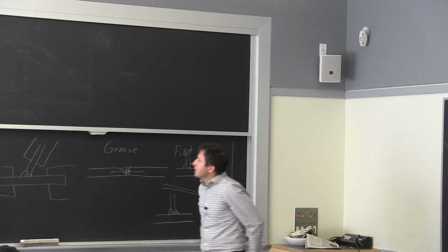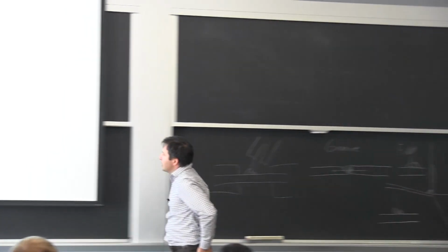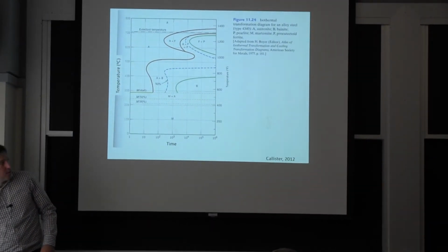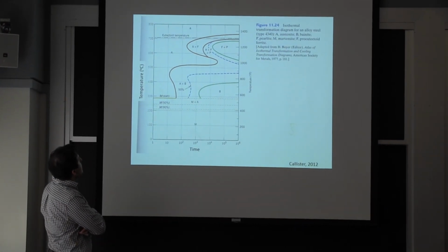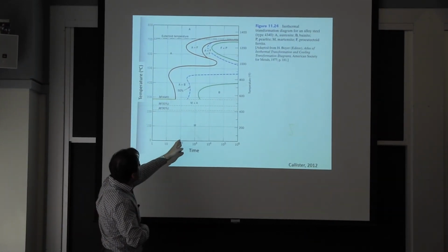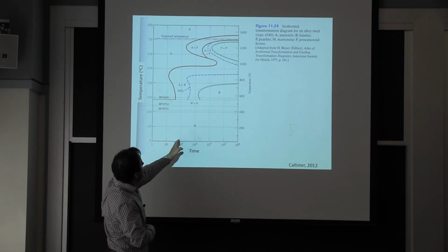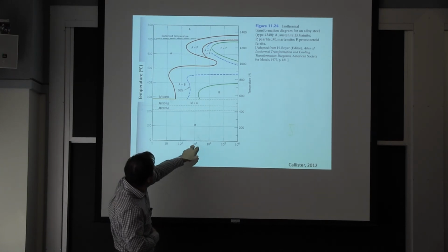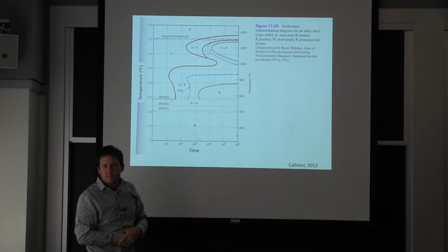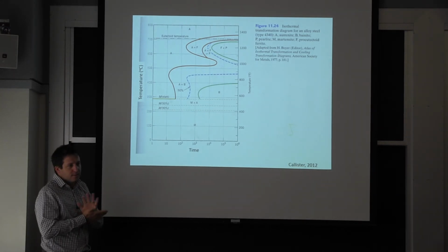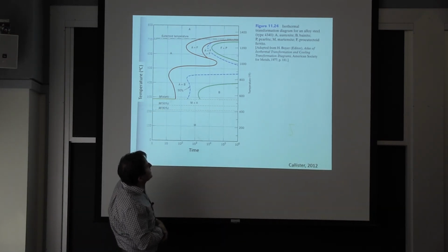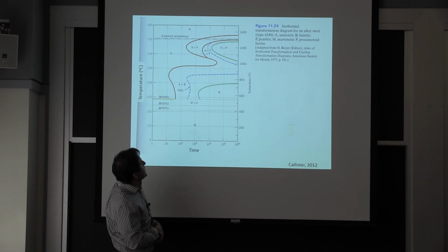Okay, so 4340. That's exactly the type of alloy steel that I was talking about earlier for landing gear. What happened here is you have 100 seconds before you start forming any ferrite or any cementite in your alloy. We're here at 1,000 seconds. That sounds pretty reasonable, 20 minutes, right? I've got 20 minutes to cool my low alloy steel and avoid the transformation to pearlite.